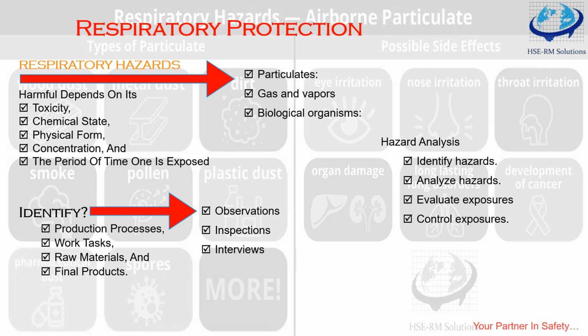It is determined by the assigned protection factor of the respirator or class of respirator and the exposure limit of the hazardous substance. Be sure to select a respirator for employees that maintains their exposure to hazardous substances in air below the MUC, the maximum use concentration.